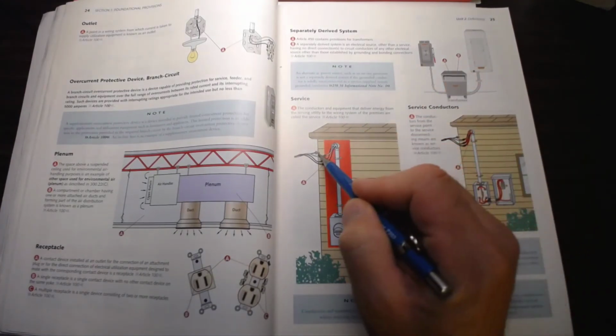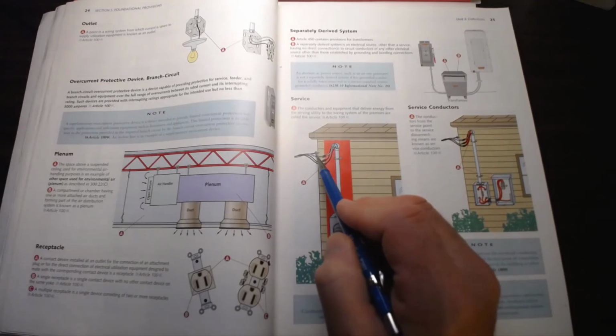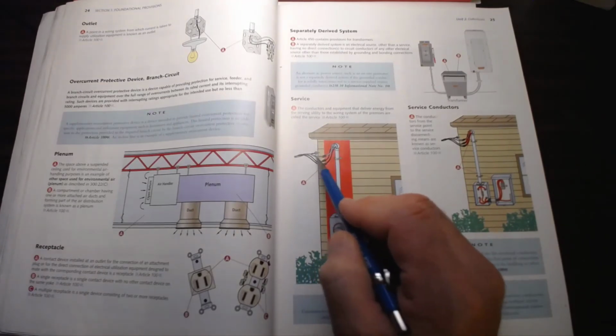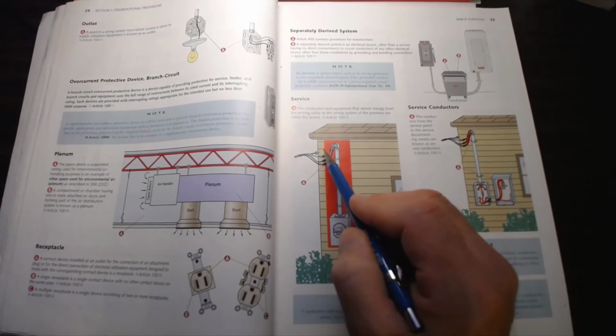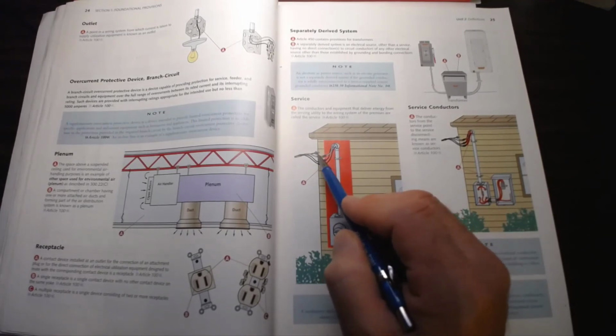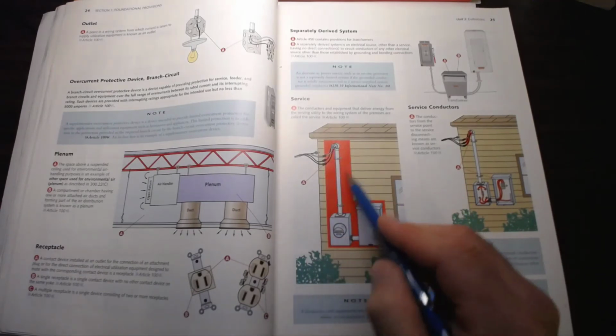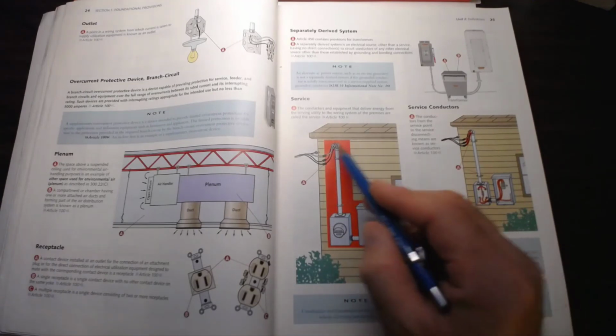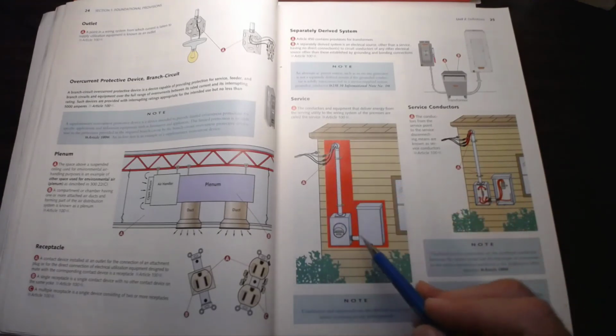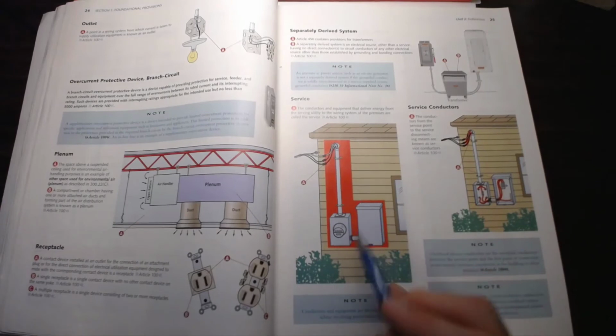point. And the other point is that you would not use a lag bolt or a lag eye here to connect into the house for the neutral, which is the guy wire, the bare metal guy wire in the triplex. That needs to be connected directly to the riser with a special clamp. And so this does not show you how every single installation is. This is giving you what the definition of those are.